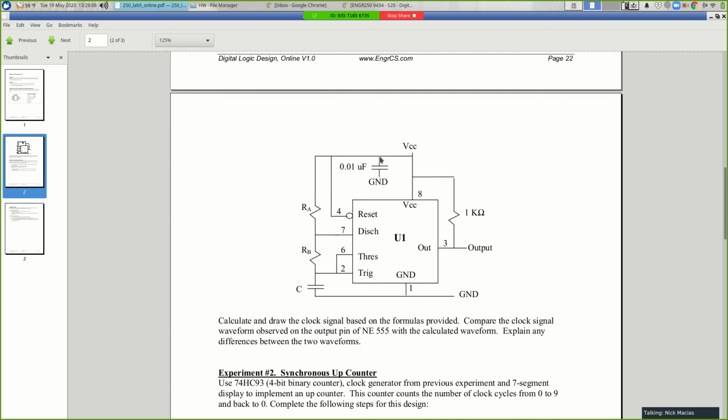Okay, and that's what this capacitor right here is doing. This is right here to basically deal with fluctuations in the power supply. Because look, it's connected between ground and 5 volts. Well, we don't normally connect things between ground and 5 volts because that seems like a short. But there's no connection between here and here because there's this air gap inside the capacitor. But if the voltage supply starts to fluctuate, if it starts to drop a little bit, this thing will actually supply extra current, bring the voltage back up to 5 volts.